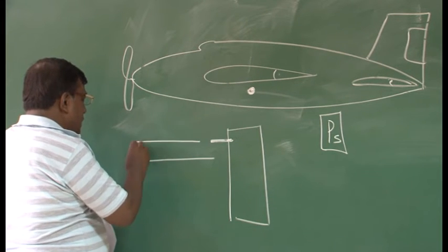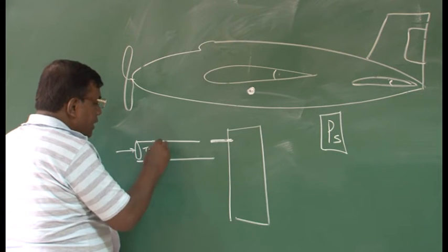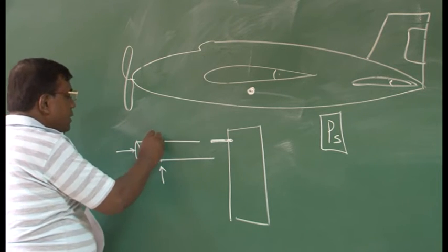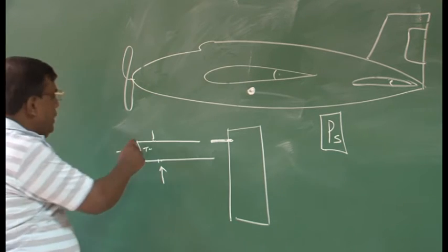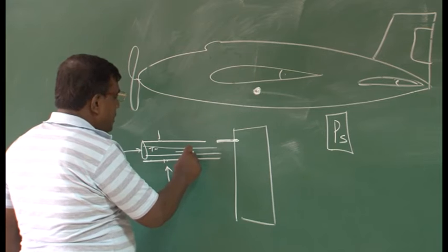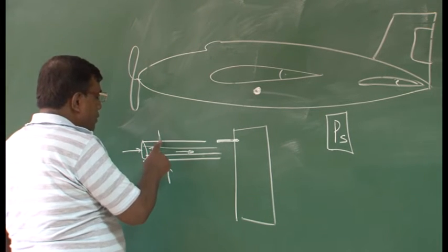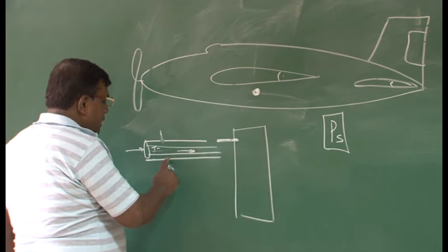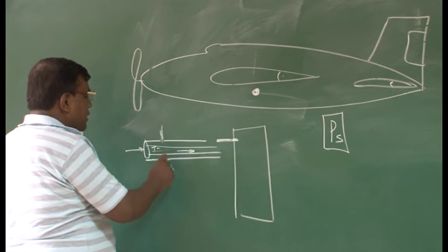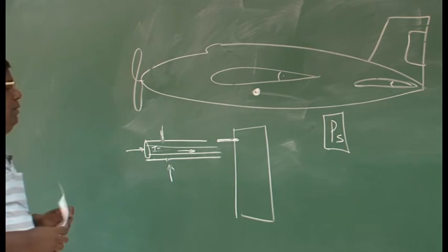So this is the inlet for total, and there will be some gap here from where the static input will go. Okay, so basically there should be two tubes like this. From here, whatever is going inside is total, and from here, if I keep a slight opening, this static pressure would be measured. There are many variants, but what is important?